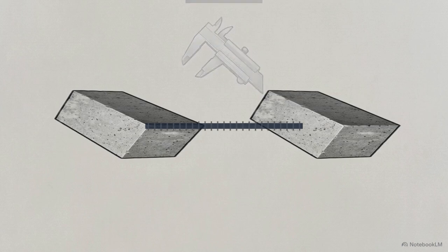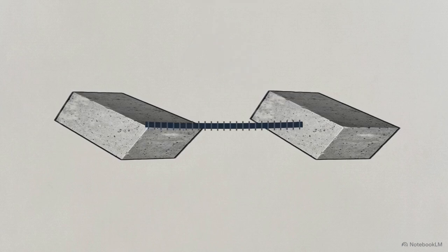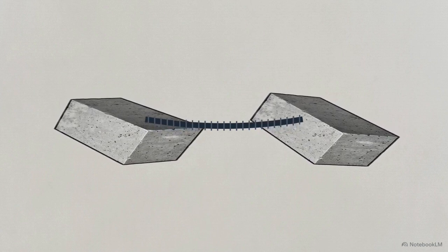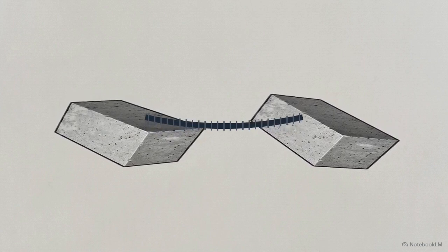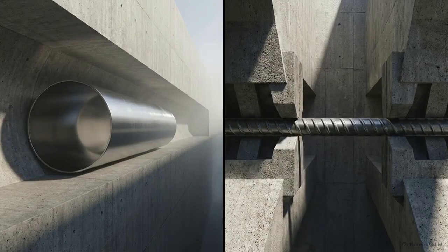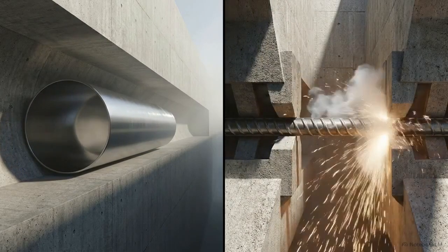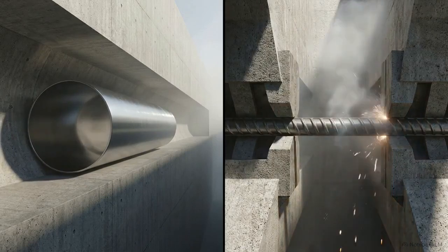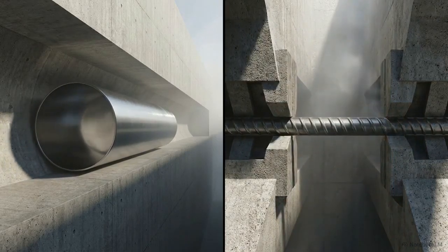They need to remain flexible enough to bend slightly when the surface heats up and causes the slabs to warp angularly at the edges. The mechanical dichotomy is clear. Transverse dowels must slip to absorb expansion, while longitudinal tie bars must grip to prevent lateral drift.